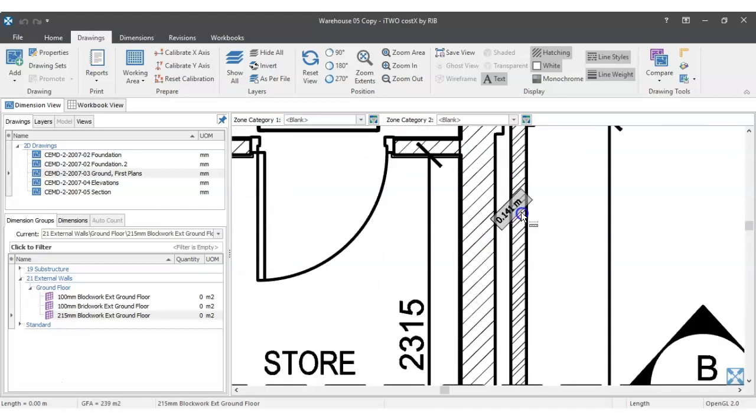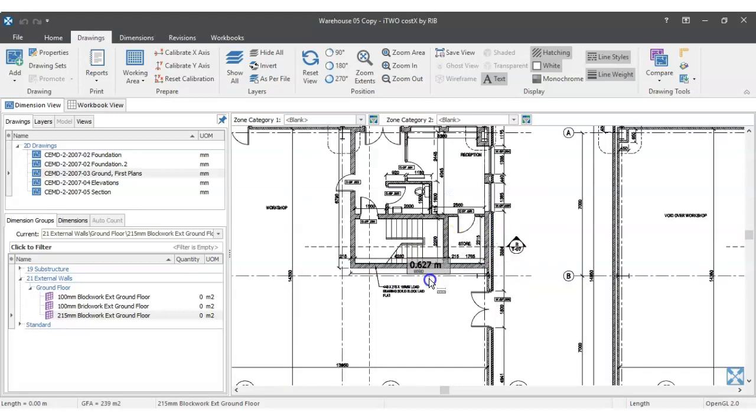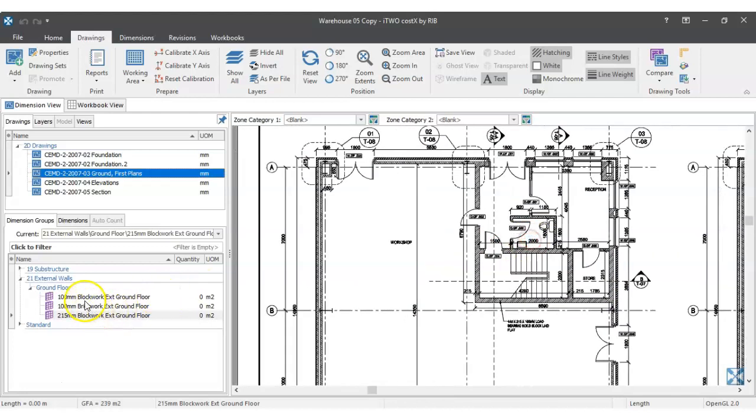It could be a cost plan where we're basically measuring the internal or center line of that cavity wall, and the description of the wall would include all those 4 or 5 different items: the forming cavities, the insulation, the outside leaf and the inside leaf. But in this case, because it's a bill of quantities measured per the ARM4, we're measuring every item in those external walls separately. So let's start with the 100 brickwork.